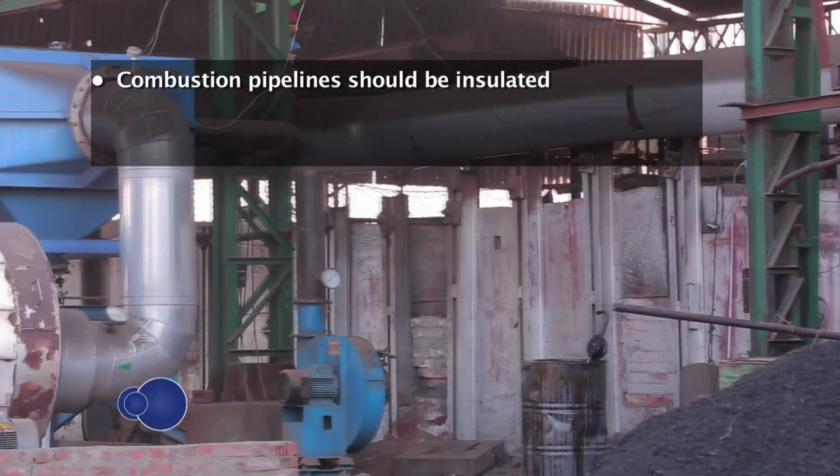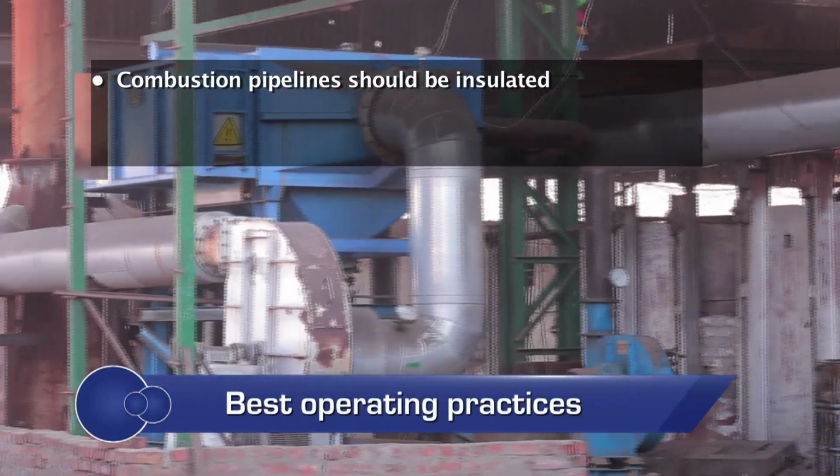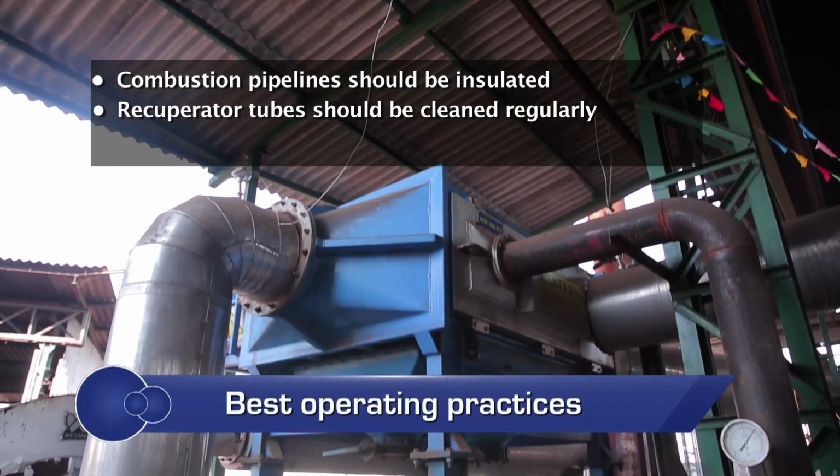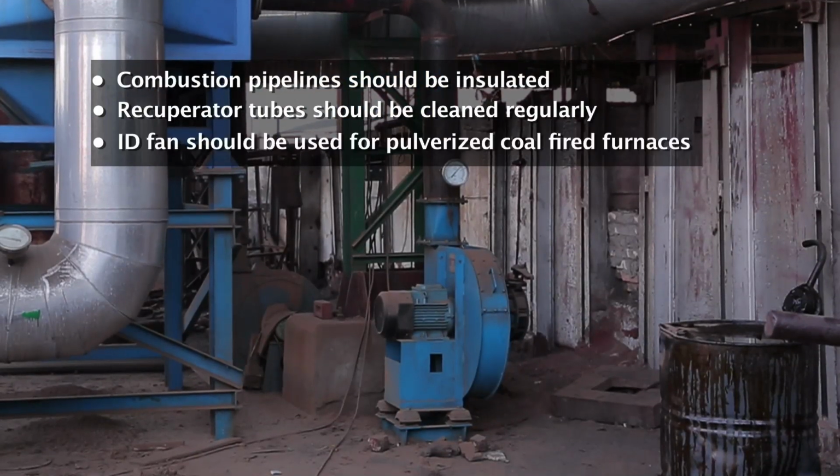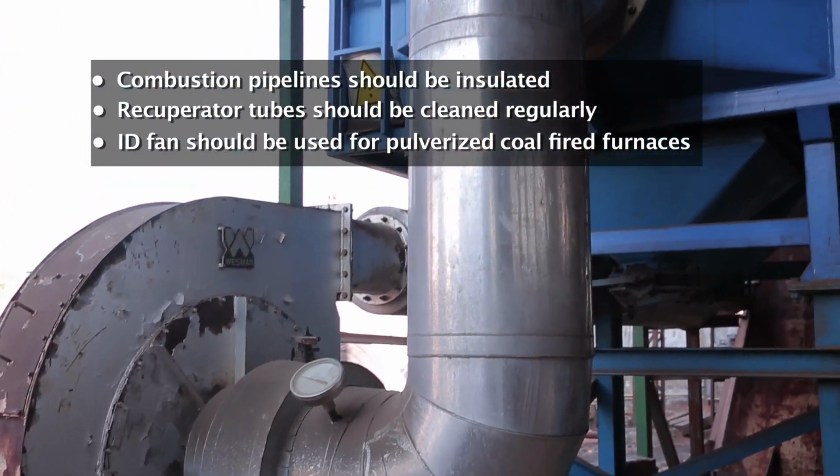All combustion pipelines should be insulated properly. Soot and ash deposits in the recuperator tubes should be cleaned regularly. An ID fan should be used for pulverized coal-fired furnaces.